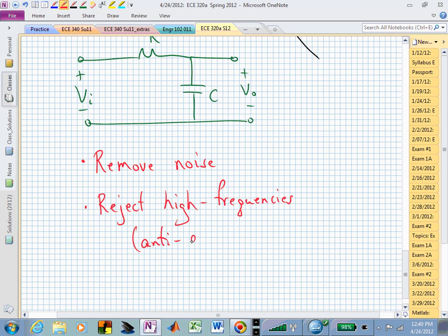And if you start doing signal processing with digital signals, you may actually want to pre-filter your waveform before you actually sample it, and that's what would then be referred to as an anti-aliasing filter, and you would want to have that break frequency selected such that you are throwing away frequencies above, let's say, the Nyquist frequency. And that would then be helpful in not having high frequencies actually after sampling look like low frequencies.